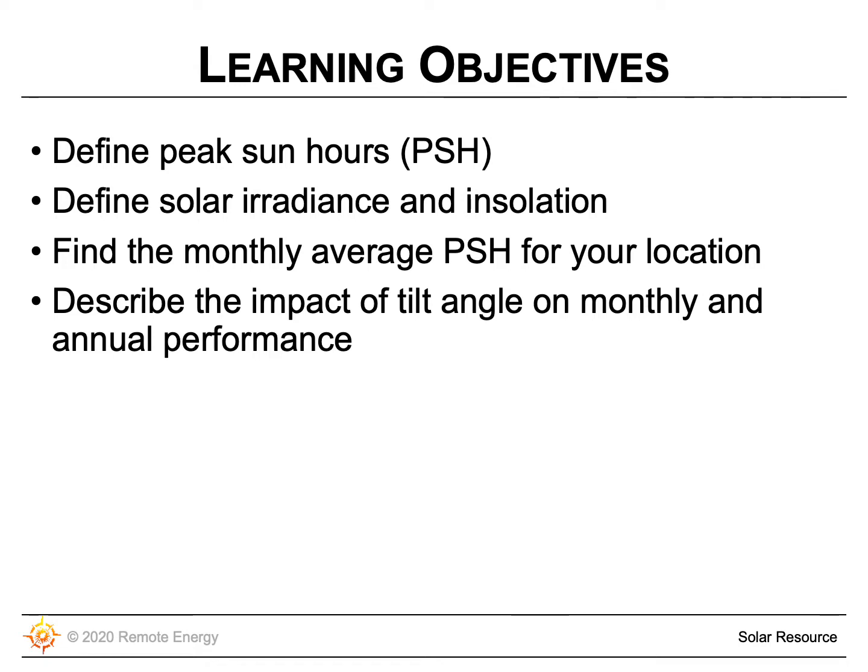One of the very important skills you should gain from this presentation is the ability to research and find out the monthly average peak sun hour value for your location. So you should be able to find a resource that can tell you how much sun is available at your specific site. And this is very important when we move on to talking about system sizing.